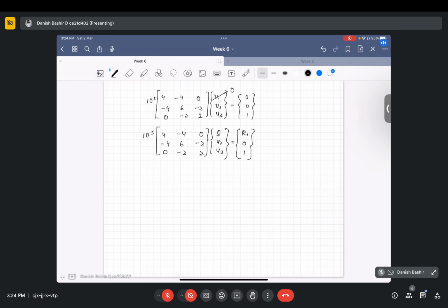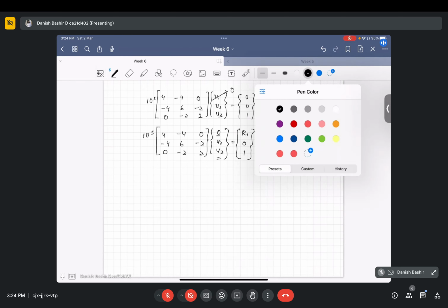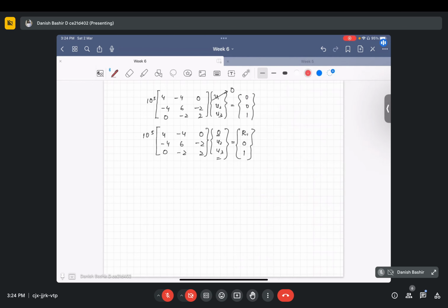So here is a simple trick. I will teach you what that trick is. Whenever there is any entry in the displacement vector equal to 0, you just cancel that row in the stiffness matrix and cancel that column in the stiffness matrix. Like here, element 1 is 0, so the first row and first column will be removed. Rest you take everything. So our system will reduce after applying boundary conditions.